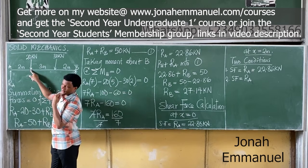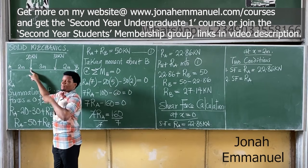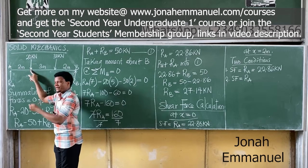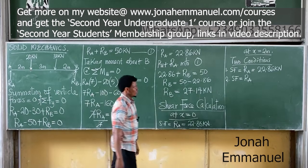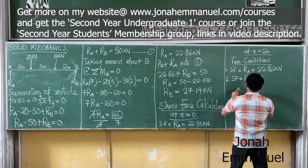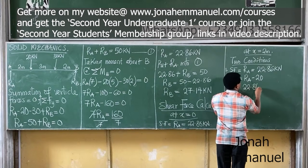At this point, do you have a force there? That's a point load. Going up or coming down? If it's coming down, should it be positive or negative? Negative. It becomes minus 20. So RA minus 20, that's equal to 22.86 minus 20.